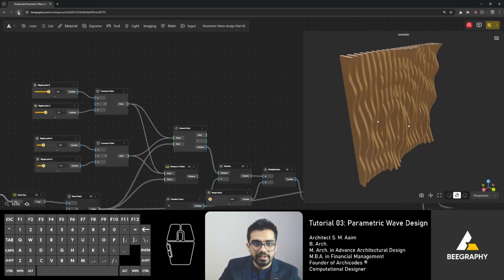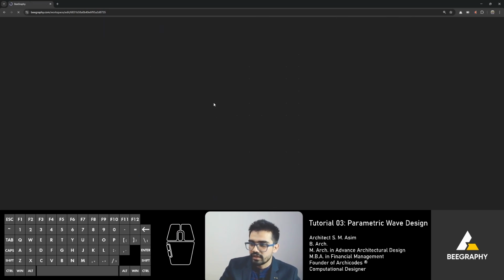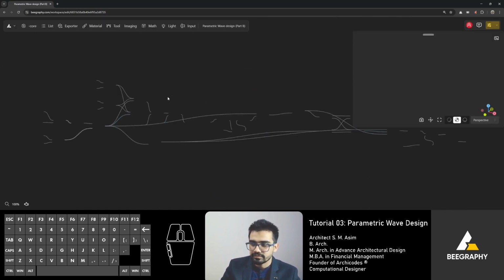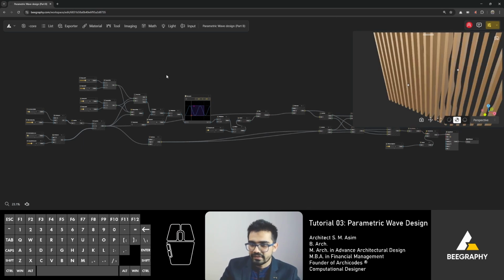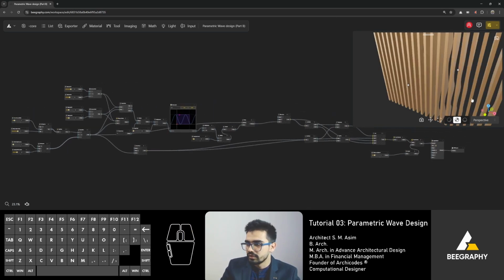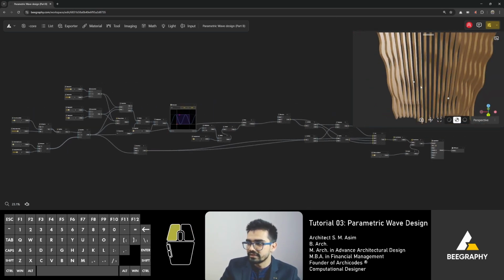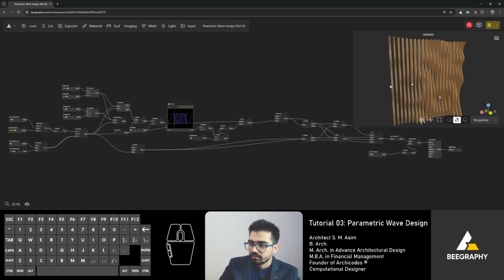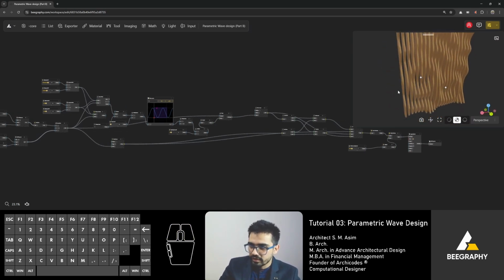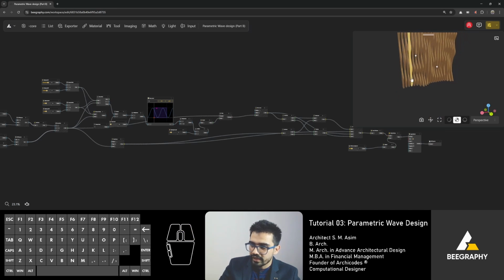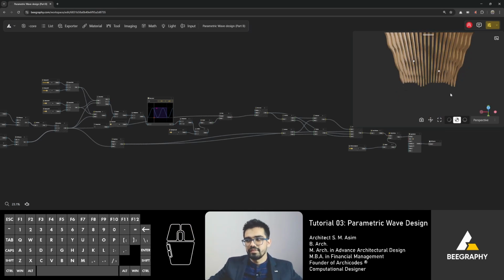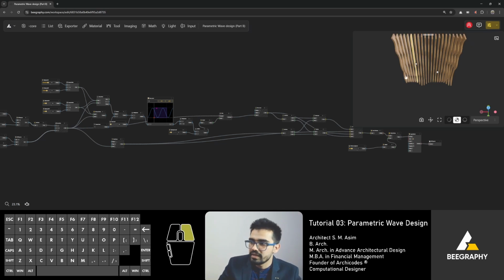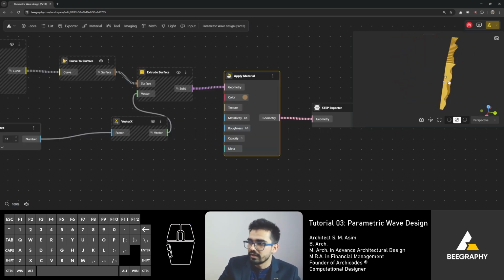See, there is some glitch. Let me just refresh the page and that will fix it. All right, that's a task for you. You need to generate attractor points randomly in this rectangle. I'll quickly give you a run around. When you create the rectangle, create it on the XY axis and then rotate this entire thing and place it behind this wall.